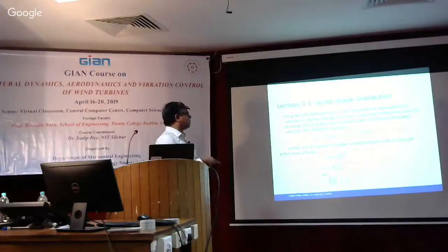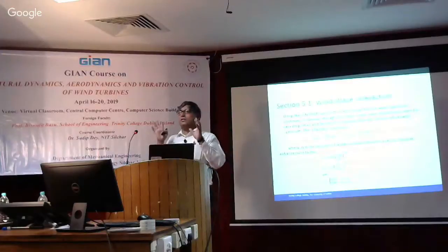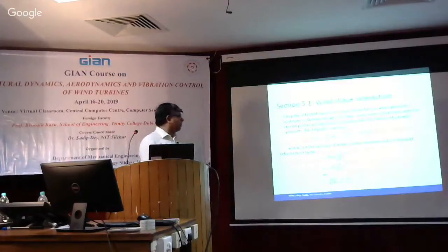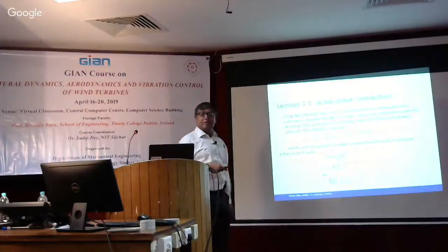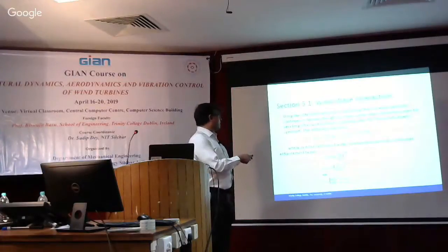So now you understand the spectrum, which gives the variation of the energy of a stochastic process over various frequency ranges. We have seen the wind spectra, and in waves it is called the Pierson-Moskowitz spectrum. The spectrum gives you the amplitude as a function of the frequency omega, and then you have certain parameters which depend on the water surface elevation.